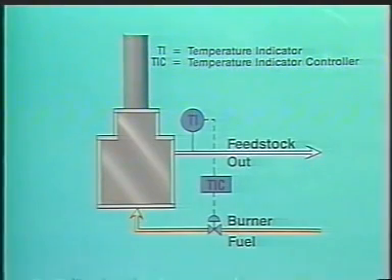There is a target outlet temperature for the process flow, and this is used to determine the amount of fuel going to the burners. In an automatic control scheme, the outlet temperature is monitored by a temperature controller, which controls the flow of fuel to the burners. In order to increase the outlet temperature, more fuel is burned. To decrease outlet temperature, less fuel is burned.